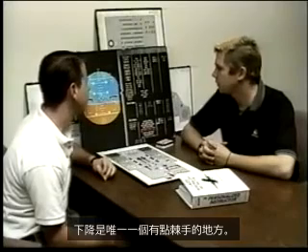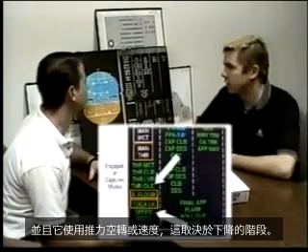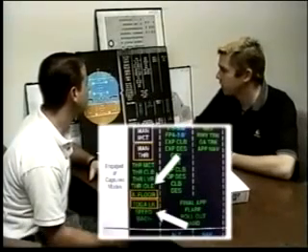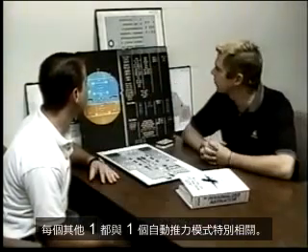Descent? Descent's the only one that's kind of tricky up there, and it uses thrust idle or speed, depending on what phase of descent it's in there. It's the only one. Every other one is associated specifically with one auto thrust mode.